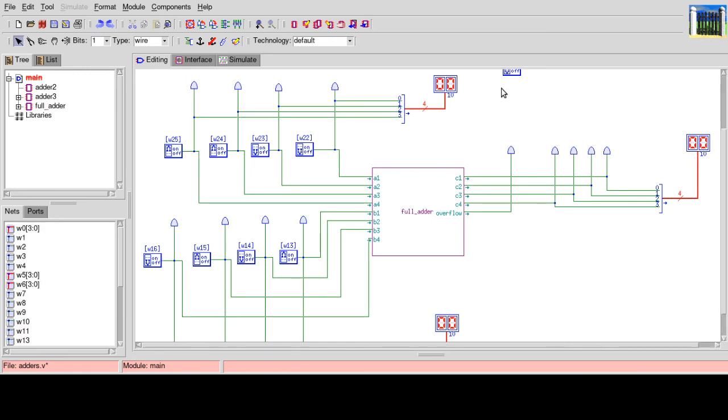Finally, you want to see this thing in action. So here it is. Now, it's a little hard to see everything that's going on here. Let me just describe what we have. First, this box here in the middle, that is your full adder. Now, what do you have to feed into that full adder? You have to feed it with the first number, the A number, and the A number is made up of A1, A2, A3, and A4. So the first number has 4 bits. The second number also has 4 bits. So that's your B1 there, B2, B3, and B4. So you actually have to feed 8 bits into the adder in order to add two 4-bit numbers.